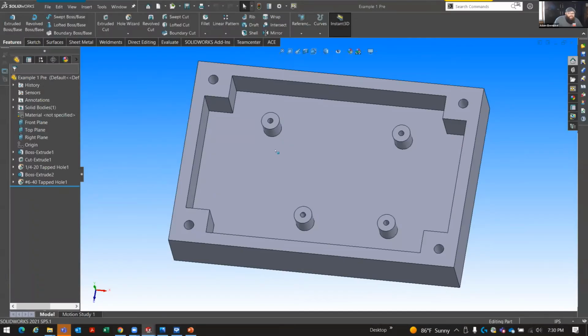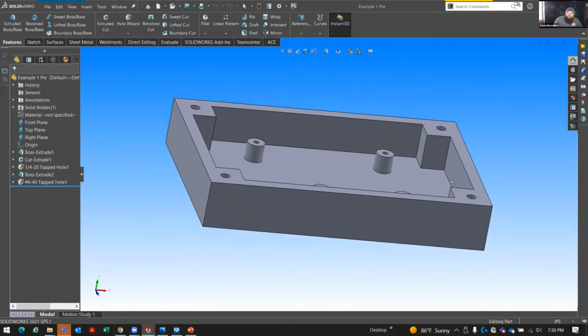So I want this cavity, right? I can send it directly to the machine shop just like this, because all the critical dimensions are there. Can it be made this way? Would it come in correctly that way? Okay, what do you see wrong that cannot be done right now? Vertical angles, hard edges, what else? Well, I mean, your vertical faces, you're not gonna get those things. Yes. You gotta change the angle of it.